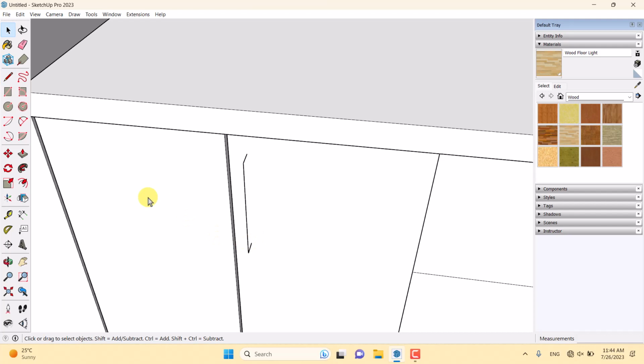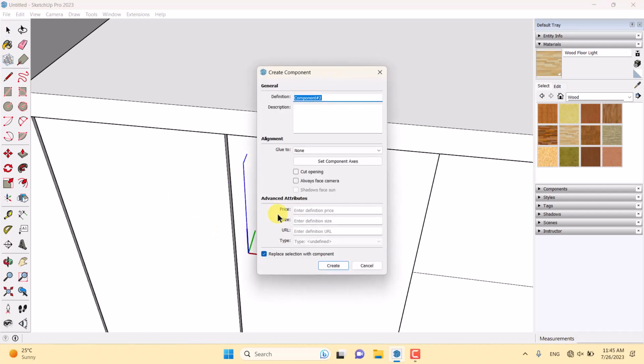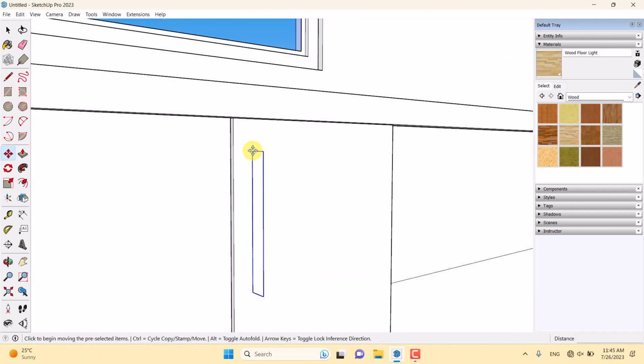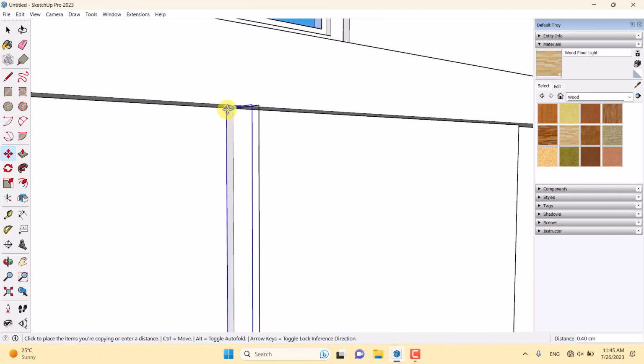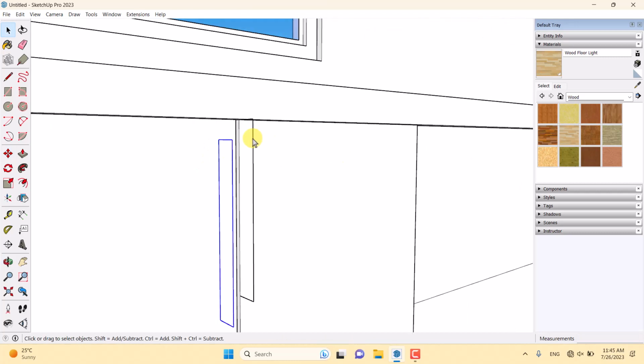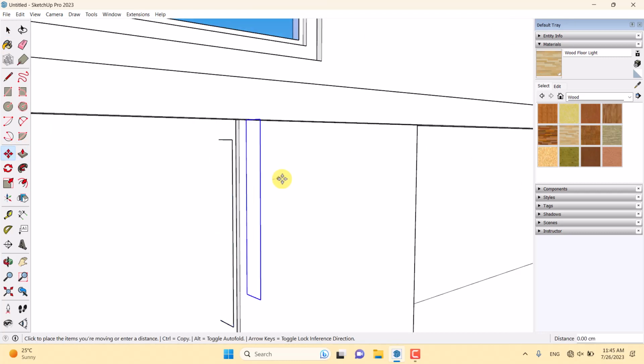And another copy on the blue axis for these big doors in here, 110 centimeter. So now I want to click on one of them, draw some circle in here, about 0.4 centimeter. And now I want to click on this path in here and use Follow Me and select my profiles.